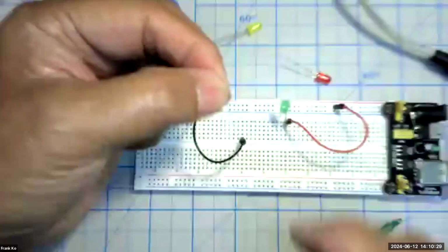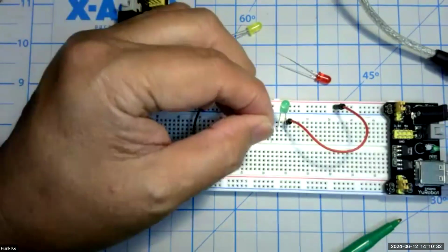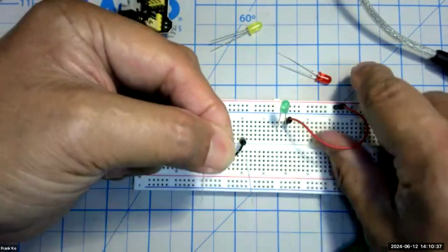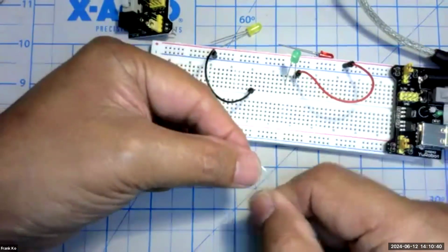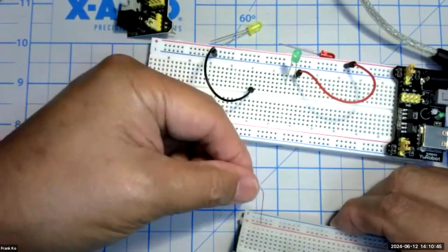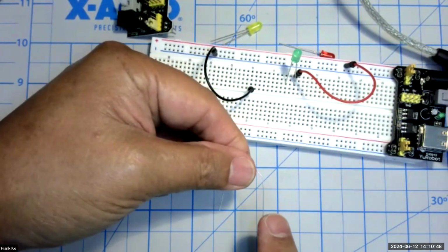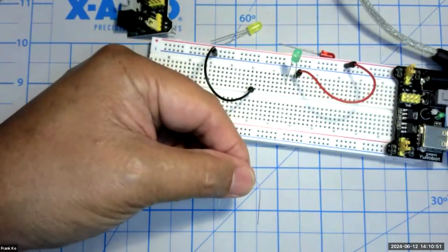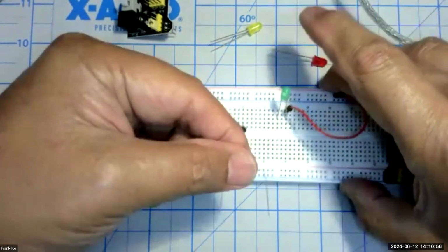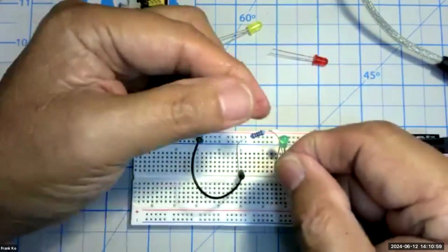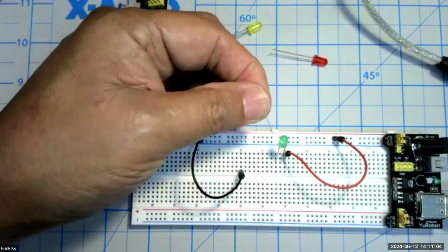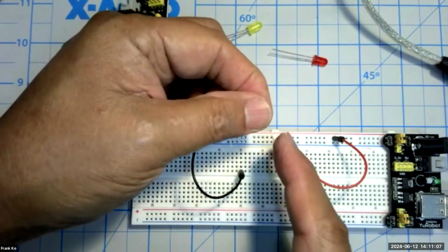So grabbing the wire very close to the base will ensure we don't crumple this wire. If we hold this at the body of the resistor like so, and we go to push this down onto a breadboard, what can happen is this wire is so thin it can crumple. And the most frustrating thing is to work with resistors with crumpled wires because they're hard to uncrumple. So there are two ways to avoid this. One way is to hold the wire as close to the end as possible, so there's a very short amount of wire exposed.